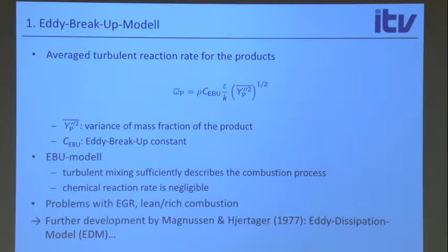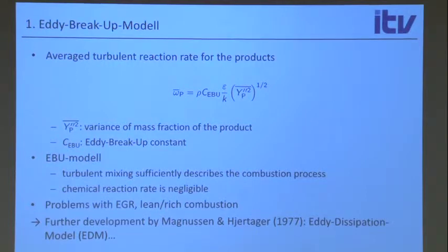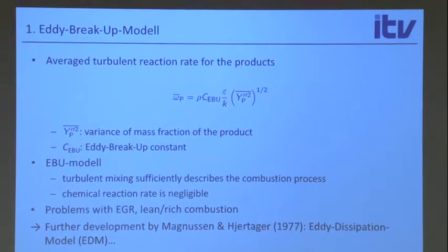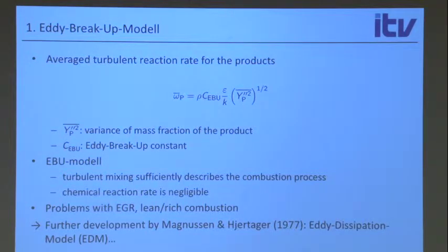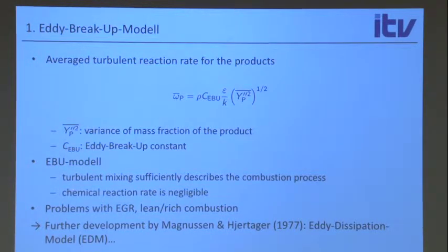So ahead of the flame, you have turbulence, maybe mixing the product a little bit in the unburned, and that will then make the fluctuation non-zero. This is when chemistry starts. It will proceed with this mixing time scale, and at some point, everything is converted. The fluctuations again go to 0, and then the source term gets 0 again. Okay? So that's how this model works. And so it has some interesting features that are not so wrong.